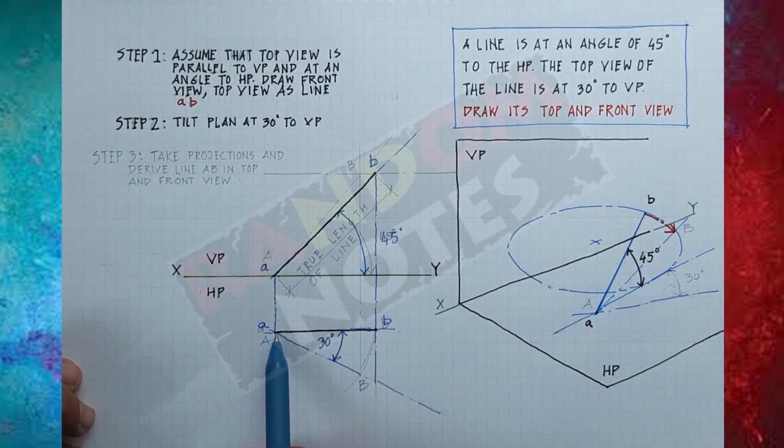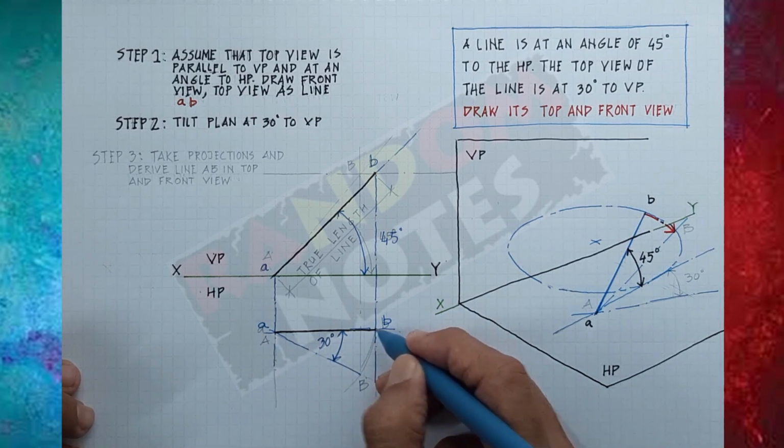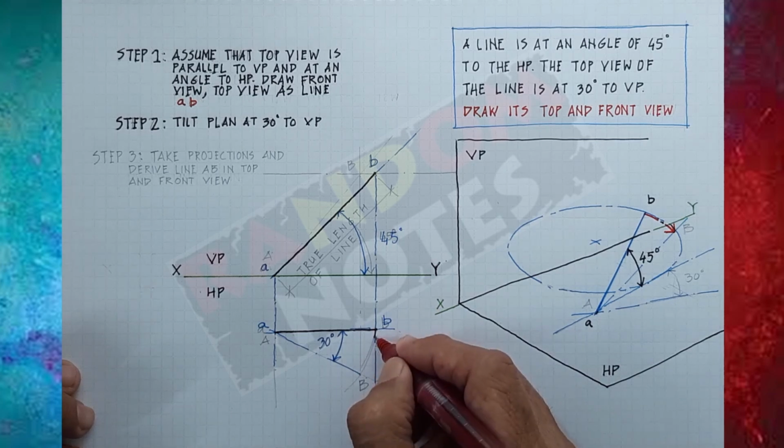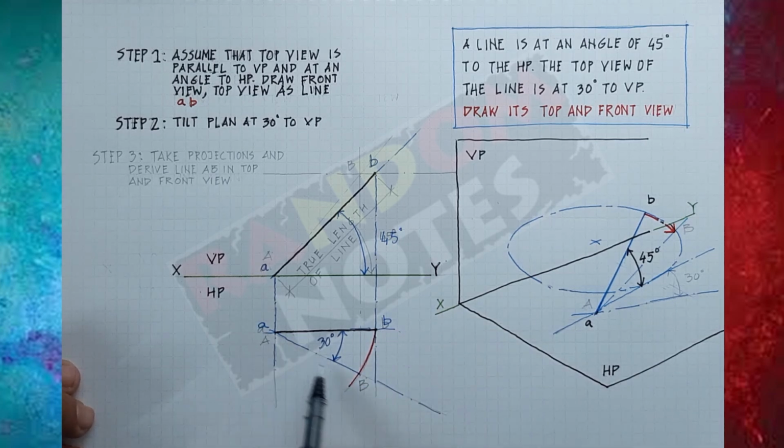So from point small a, I took a line at 30 degrees to line AB, which is this line. I take a compass, taking this as center and AB as radius, I make an arc. Wherever this arc cuts this line at 30 degrees, it will give me a point which is here, and this line is equivalent to this line.